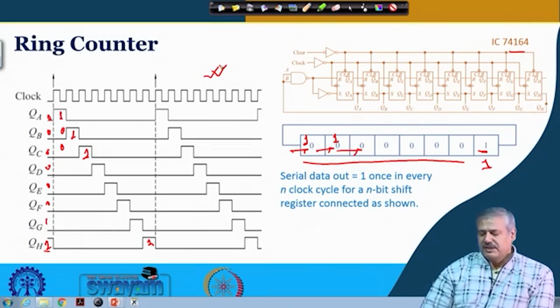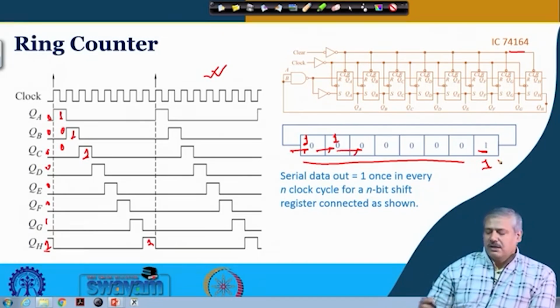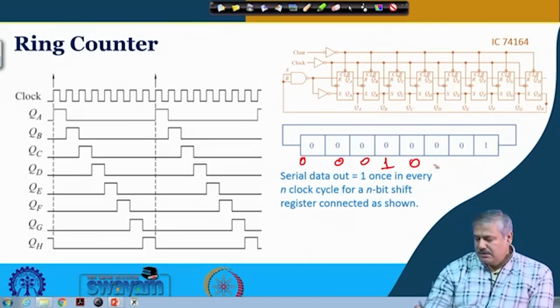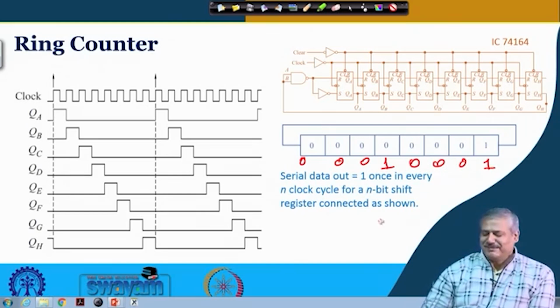Okay. So, in this case the last flip flop output, the way you have seen it, itself indicates that the count of 8 has taken place, right. So, if instead of this we have, say, 0 0 0 1 initially, then what will be the count by this particular shift register? So, 1 is coming here, and again 1 will come here after 4 clock pulses, right. So, it will be a mod 4 counter, right.